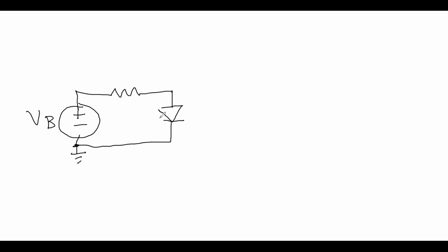This resistor is going to be called R; we're going to derive R. And remember I told you the voltage drop across the LED is some forward voltage. In our case, it's 2.1, but I'm just going to derive it generically. And then we basically just have current going through. It's just a simple series circuit. We have basically two components here, the LED and the resistor.